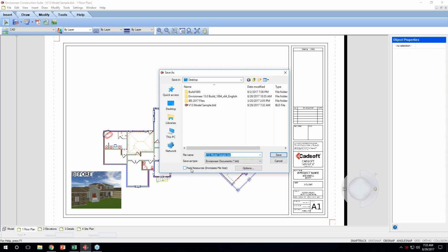And when you opened it on another computer that didn't have the same catalog, if they didn't have the same materials or the same line styles, those materials would just show as blank because it didn't have the correct material to show. So if it didn't have the brick 9 that I'm using in my model on that other computer, it would just show as white.